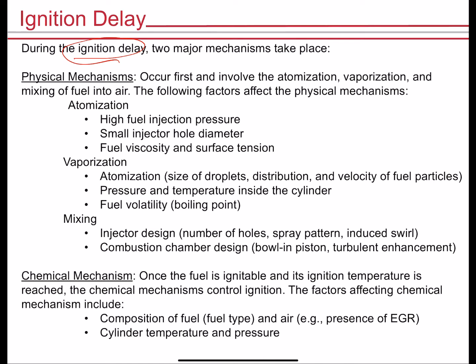And so consequently, when we talk about ignition delay in the engine world, we sort of lump everything into it. It's almost like a grotesquely averaged parameter that includes a lot of different processes, both physical and chemical. We've described a lot of this already, so I won't go through it in great detail. But the first portion of the engine ignition delay is what we call the physical mechanism, and that involves penetration, breakup, atomization, and vaporization.